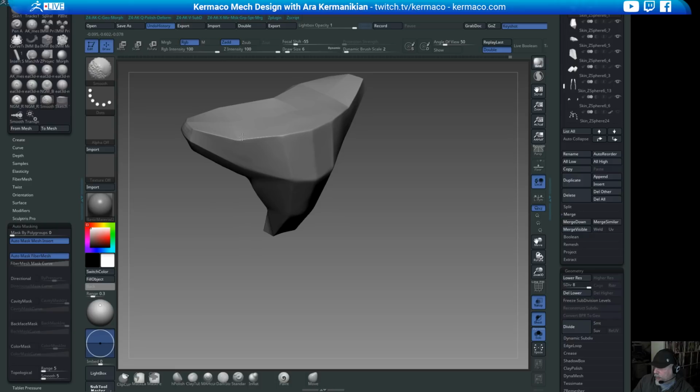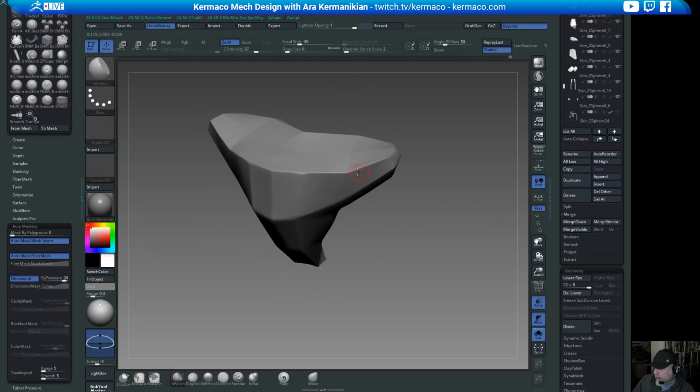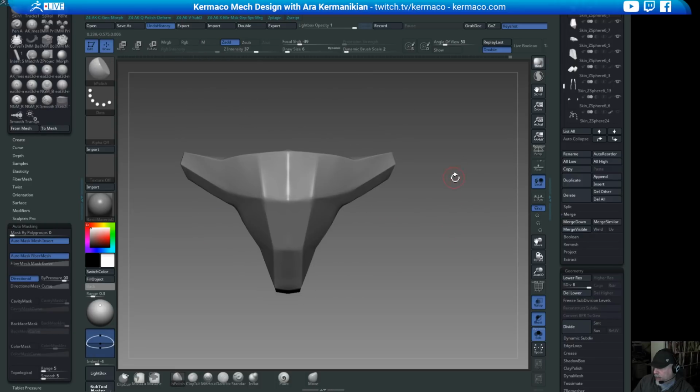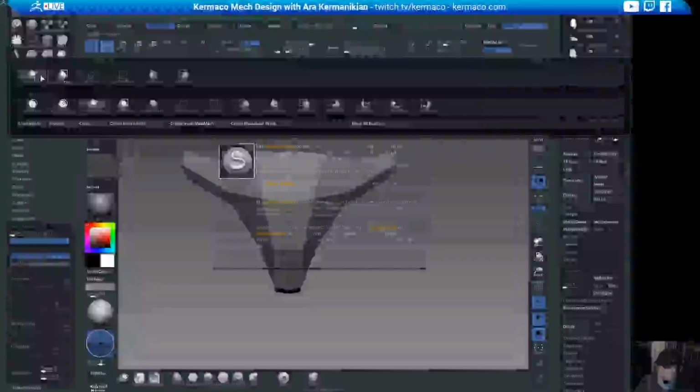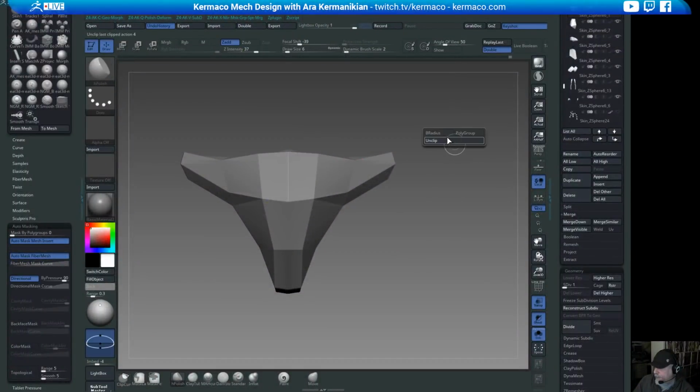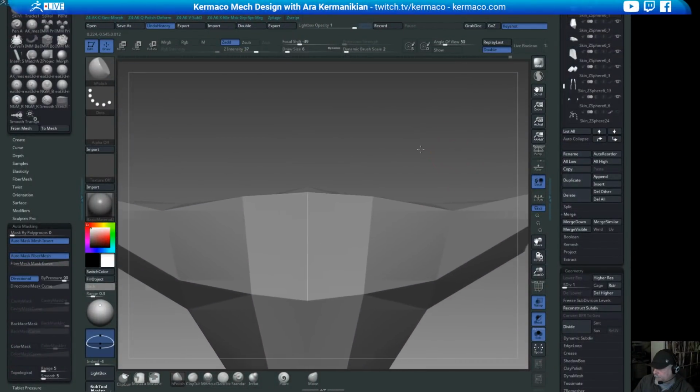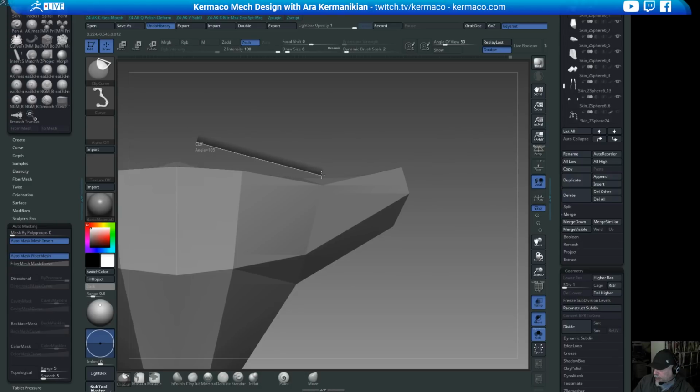Right, get that edge to work here. I'm not liking this little continuity here, so what I'm going to do is change the shape down. Basically, the silhouette of the edge is what's happening. To do that, I'm just going to use the clip curve. Just going to zoom in on one part of it, and then get the curve to work.